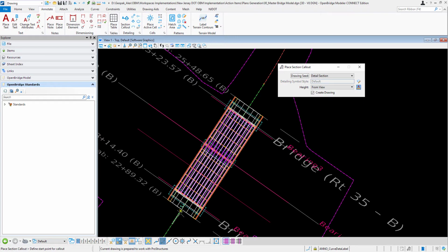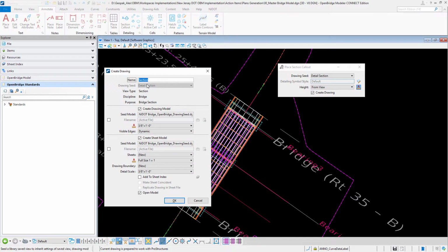Right, so from here, I just say that I want a profile view right along the center line of the bridge, just to give me all these other options, right? And then all the way to this depth. Saying that, I will call it, this is the plan elevation,